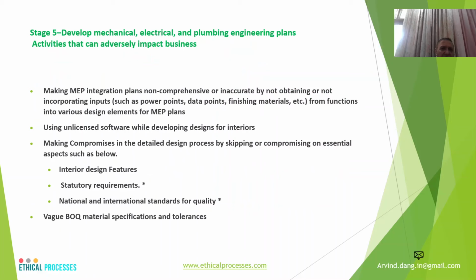Now, the fifth stage is developing the MEP plans, which integrate the architecture and mechanical and MEP plans. Here, the important aspect is that the MEP plans drawn by the interior designer may not be comprehensive or may be inaccurate, and therefore they cause issues with things like power points, data points, or finishing materials, etc.